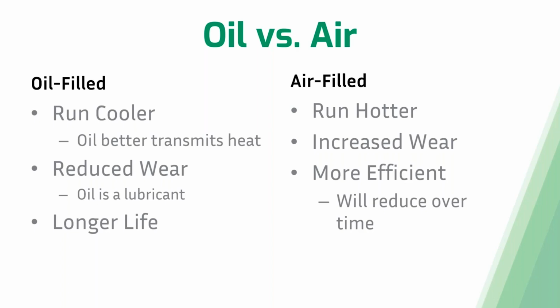Now, one thing to note is that you will see that air-filled motors tend to be a little bit more efficient than oil-filled motors. However, this is only really at the beginning of that pump's lifespan. As that pump is operating, those air-filled motors are going to reduce in efficiency over time, because of that increased wear on those internal components. Whereas with oil-filled motors, that lubricant helps prevent wear and leads to longer life and more steady efficiency throughout its life.